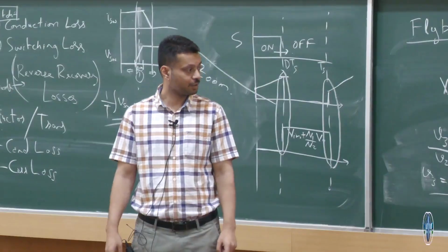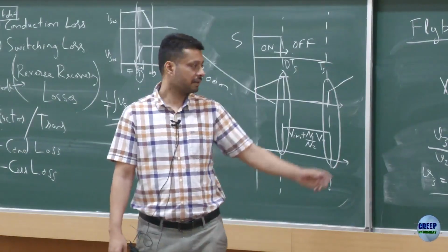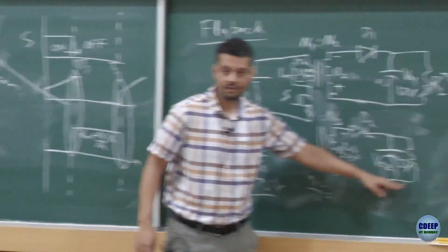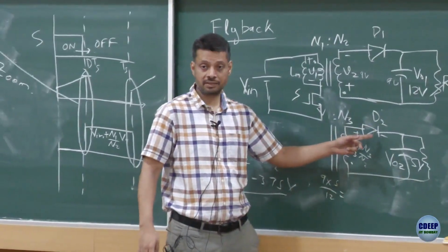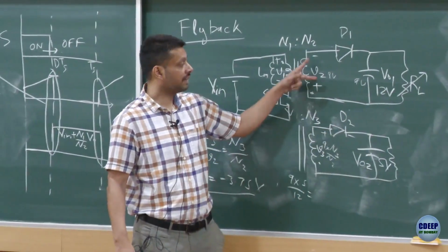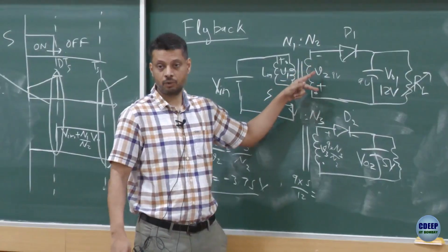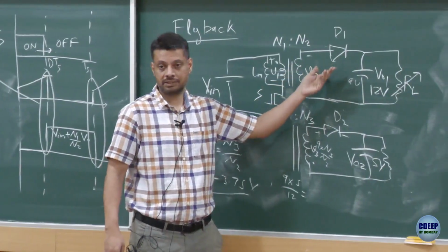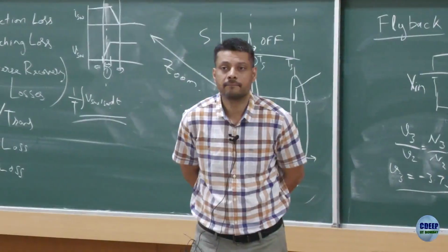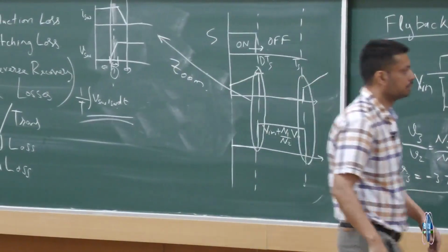It's possible with lower voltage also, same thing, 5 volt goes to 4 volt, right. Assume this diode conducts, this becomes 4 volt, you find this voltage here, you will get 11 volt, this diode will be reverse biased, so everything will flow here. Yeah, you can do that, okay, good.